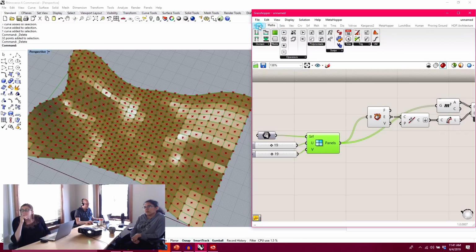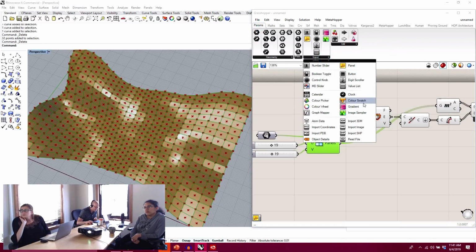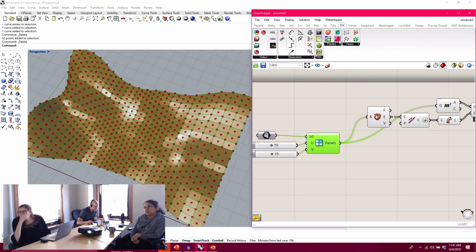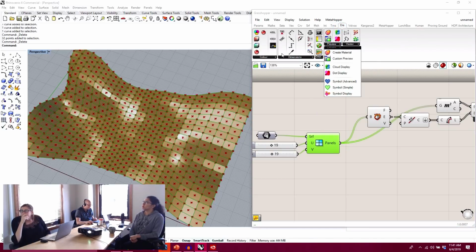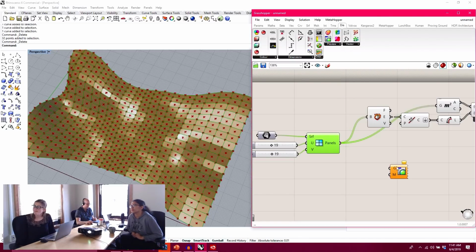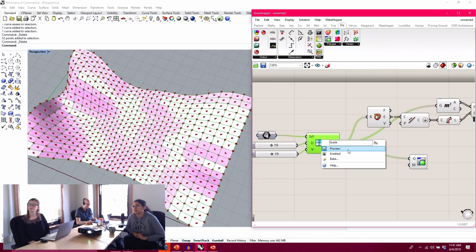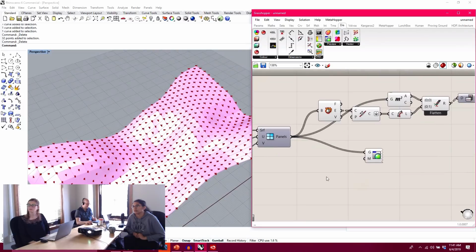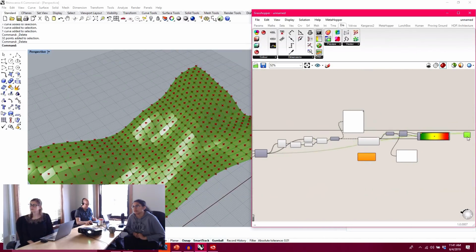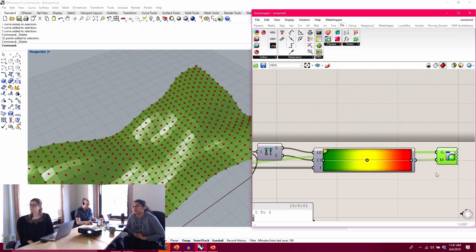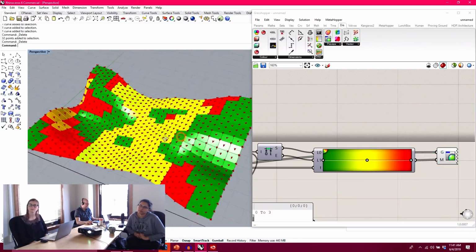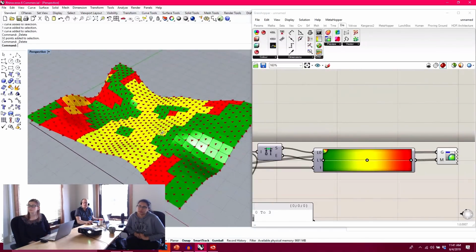And what I can do then is go here and find, let's see, let's move to display, I believe. It's going to be under custom preview. So here, as you can feed into any geometry out of the box, it's going to give you a purpley geometry. I'll disable the preview on that, like so. And if I drag this all the way over here and then pass in my color gradient, we'll start to see the outcome of how the algorithm is starting to classify these panels.